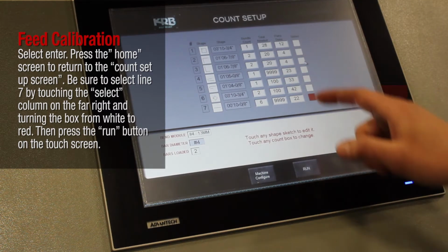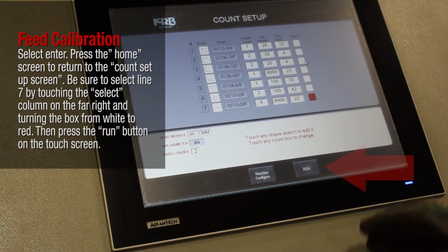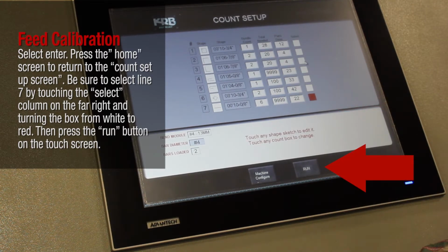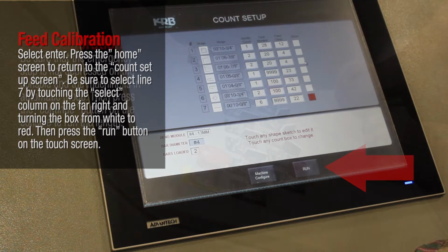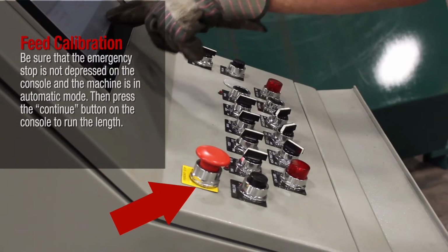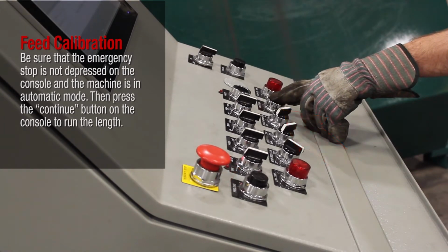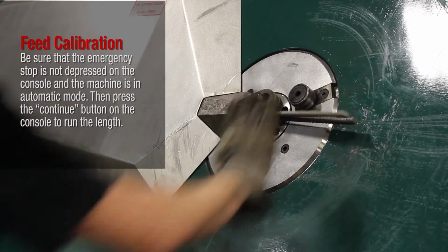Be sure to select line 7 by touching the Select column on the far right and turning the box from white to red. Then, press the Run button on the touch screen. Be sure that the emergency stop is not depressed on the console and the machine is in automatic mode. Then, press the Continue button on the console to run the length.